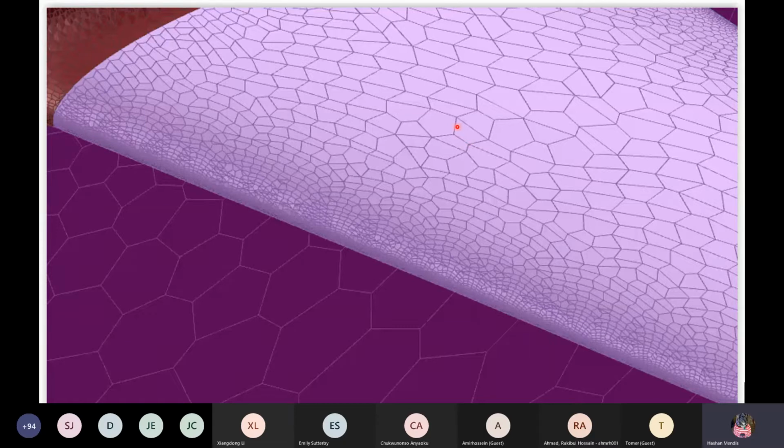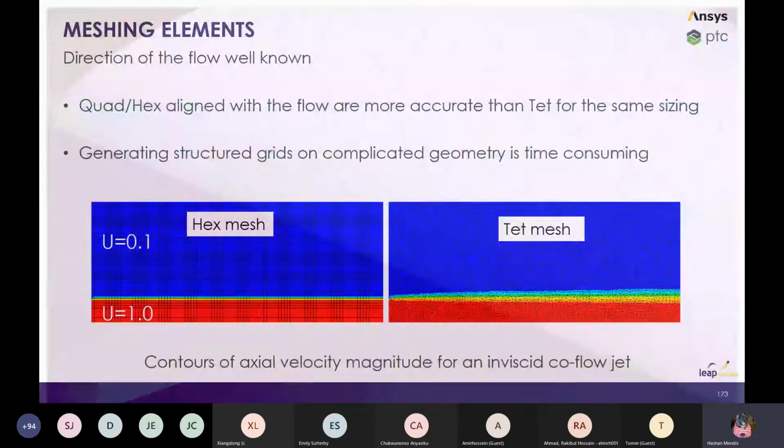So like I was saying before, what we might need to do is go back and either make the poly elements smaller, or we might need to make the mesh size, the inflation, a little bit larger, right? Or we might find that maybe instead of a polyhedral grid, a tetrahedral grid might be appropriate for this particular case, right? So again, there are always trade-offs, right? And in generating your mesh strategy, you might want to think about some of these trade-offs as well.